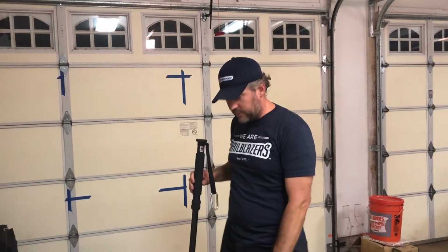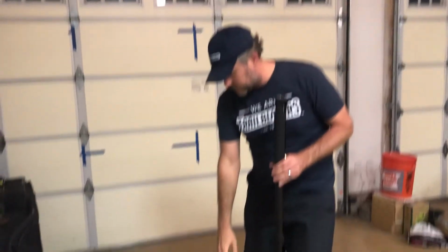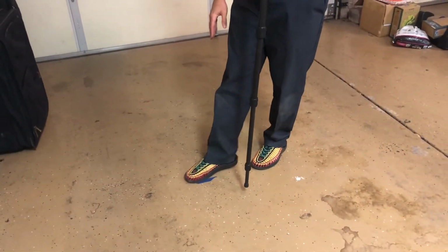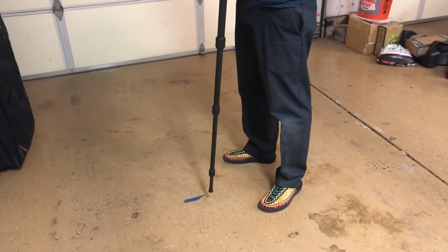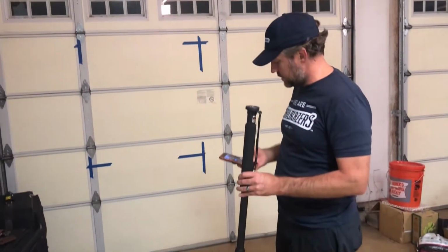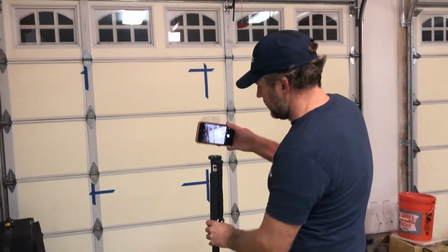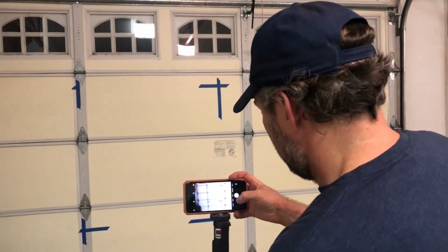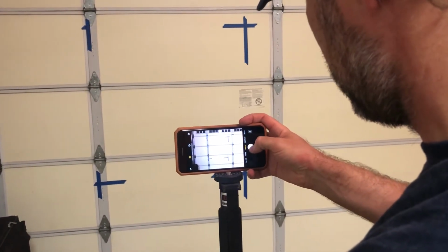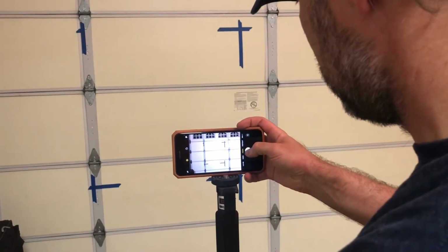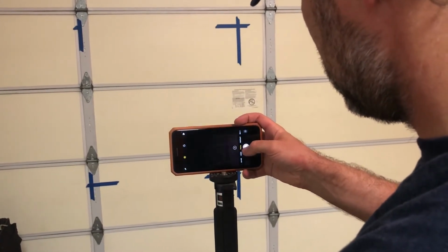And then I need to know how far my camera is from the object. So if you look down on the floor here, I've got a 2 meter mark marked out in tape, and basically all I need to do is know those dimensions, and then I'm going to come over here and try to center up as best I can on that square, try to make sure there's not a lot of tilt to my camera, and then just take my photograph. And then we're ready to bring that photograph into Blender and try to match it with our camera.